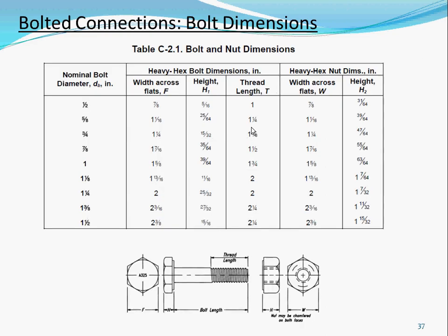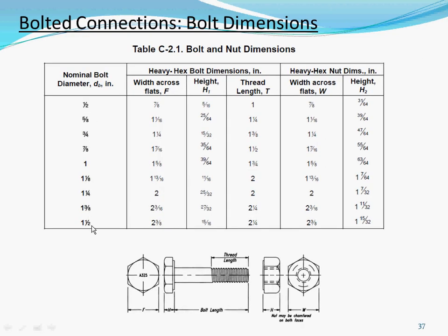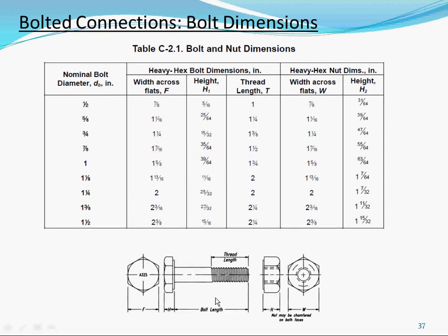Bolts typically go from 1/2 inch to 1.5 inches, so anything smaller is not covered by the RCSC. That's the range. The geometry is noted here as well. You can see what we are using in our connection is mostly 7/8 for the structural, for this end plate connection, and then for the connection to the beam.